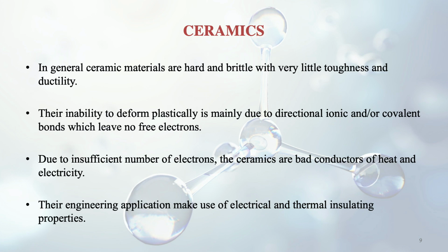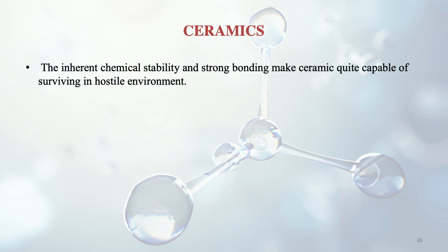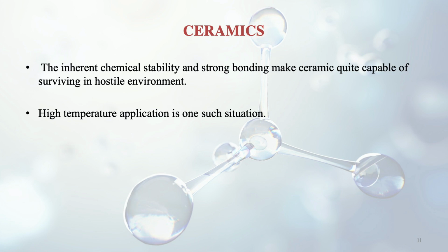This is quite obvious, because electricity conduction is based on the movement of electrons only. Their engineering application makes use of electrical and thermal insulating properties. Since they are not good conductors of heat and electricity, they can be used as insulators. The inherent chemical stability and strong bonding make ceramic quite capable of surviving in hostile environments. In the molecular structure they have very good chemical stability and strong bonding, so they can be used in hostile environments or high temperature applications.